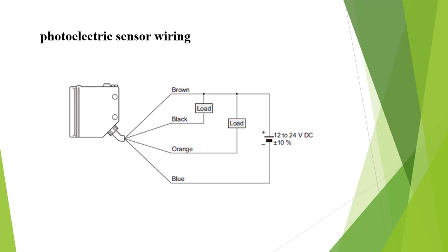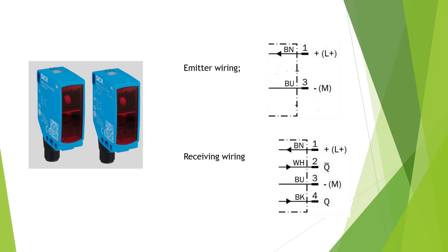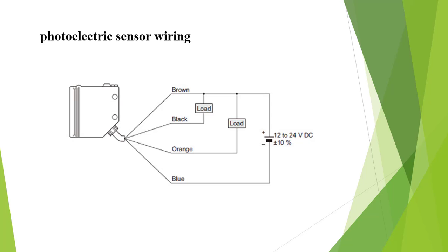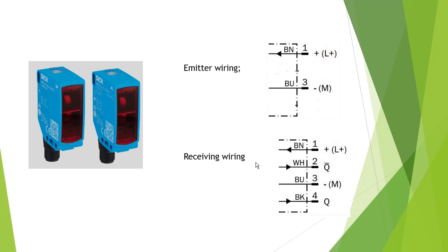All of this is the photoelectric sensor. The same thing applies to PNP, NPN proximity sensors. In the future, we will talk about how, if you have a PNP or NPN proximity sensor and you don't know which kind, we can check. Use the multimeter to identify this. The proximity sensor is NPN or PNP.